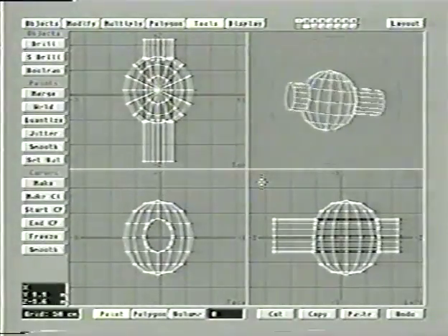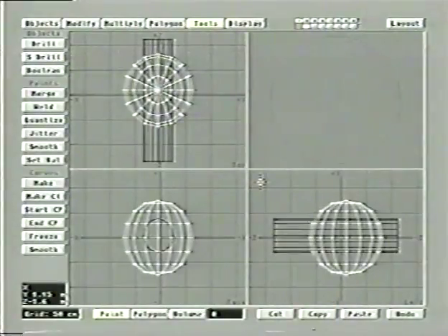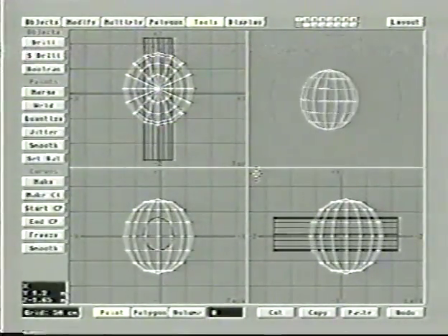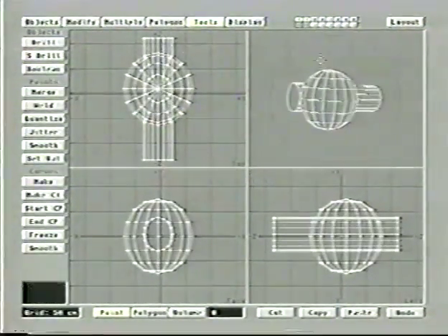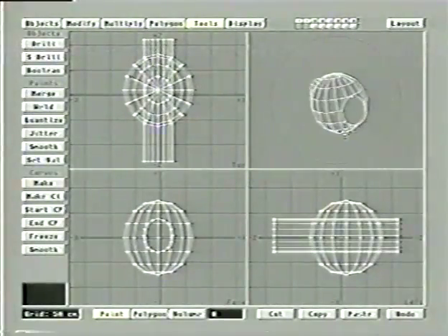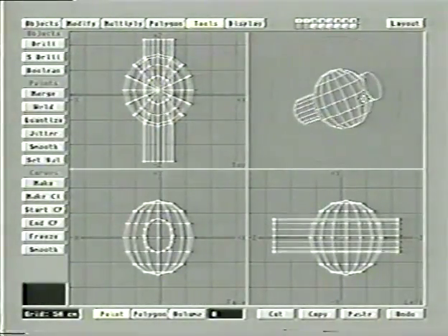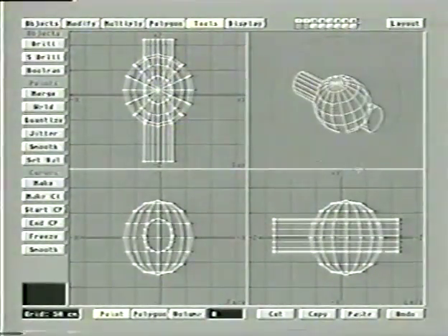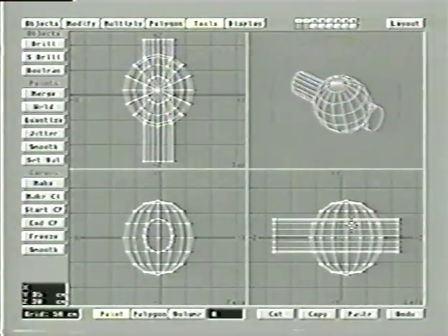And this is actually another fairly handy tool to use. There's a number of reasons you'd want to do this. If we just had these two layers combined, for instance, let me undo this. We undid this and just selected both layers as active. The final effect would end up looking about the same. There would be very little difference in the final effect, except the polygons that are inside here are completely useless. So we can use union to get rid of interior polygons, which can be handy.